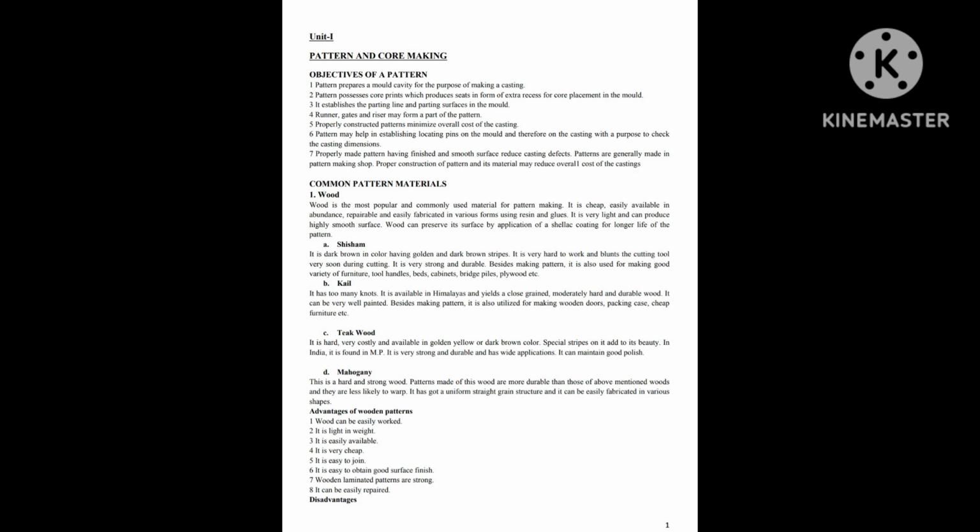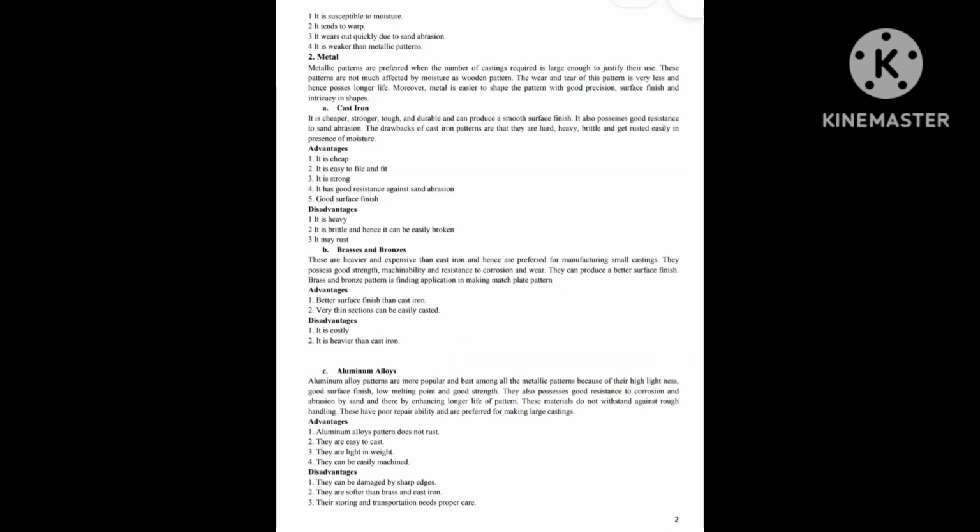Advantages of wooden patterns. 1. Wood can be easily worked. 2. It is light in weight. 3. It is easily available. 4. It is very cheap. 5. It is easy to join. 6. It is easy to obtain good surface finish. 7. Wooden laminated patterns are strong. 8. It can be easily repaired.